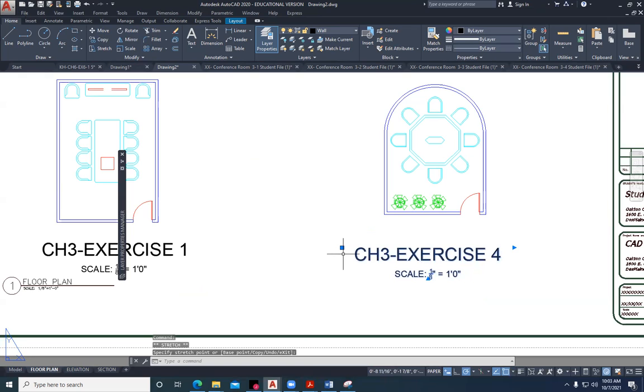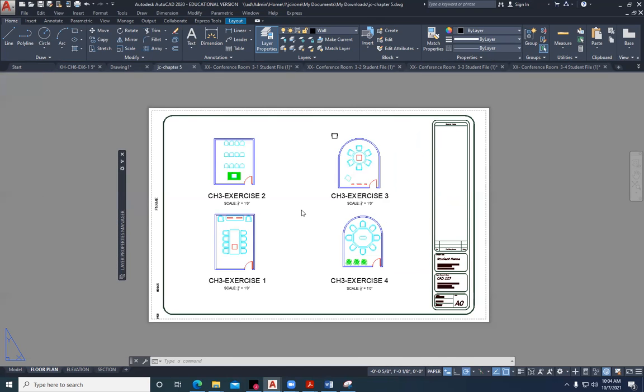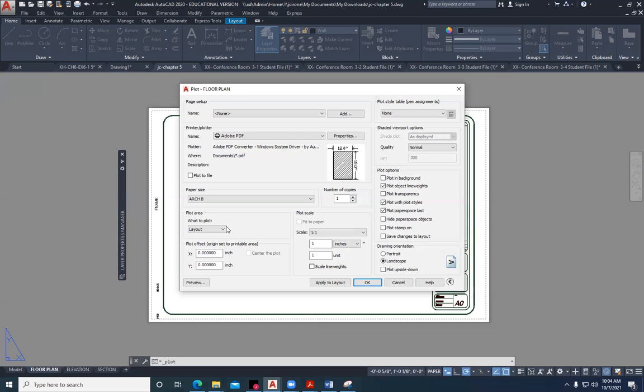And we're just doing this kind of on the fly. It might not match exactly to the book, but the technique is what we're trying to show here. This one's different. I do have them, but it's just a matter of being able to set this up. I like when everything matches, so I'm going to bring this down so it's about the same level. And then what we want to do is update the title block information. With that, I'm going to take this part out. I don't think we'll need that. That's the basic rundown on how to create viewports for our drawing in Chapter 5. I'm going to sign this with my initials on it.